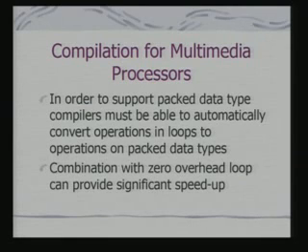Next, we shall look at multimedia processors. In fact, the majority of multimedia processors today use what are called packed data types. We have looked at packed data types in the context of Pentium processors also, with MMX enhanced instructions, where I can pack multiple bytes or multiple integers together into a single word and use a single instruction to operate in parallel on the multiple data elements packed into one word.